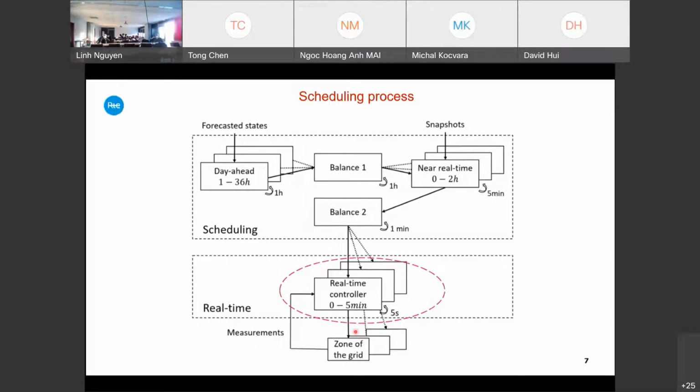And then we have some upper level scheduling. Mostly for the moment, this is used for the batteries. So for the batteries, we have to prepare the battery. If we expect a congestion in the future, we have to empty the battery, to discharge the battery in advance. During the congestion, the battery usually will be used to charge, to have less power on the grid.